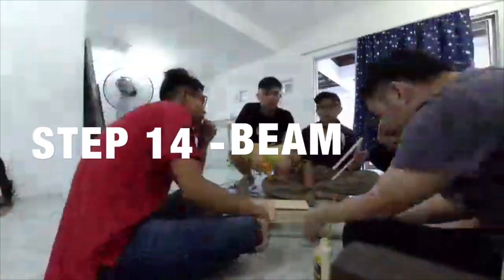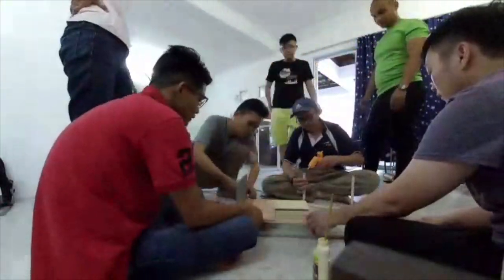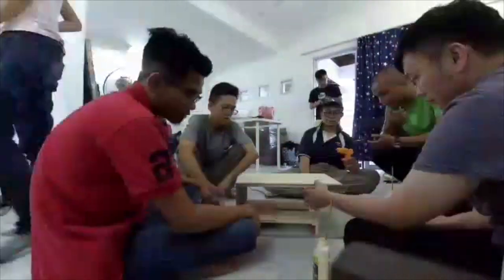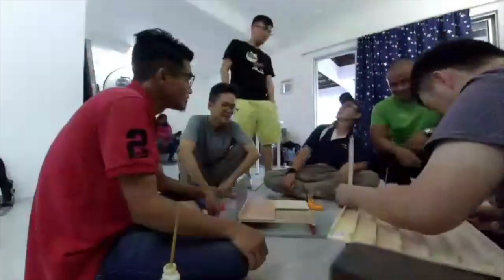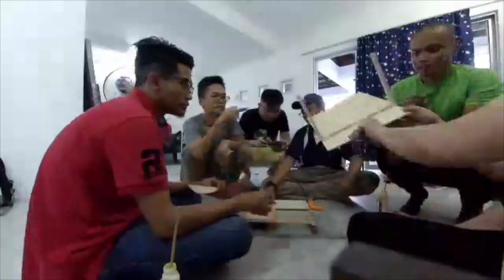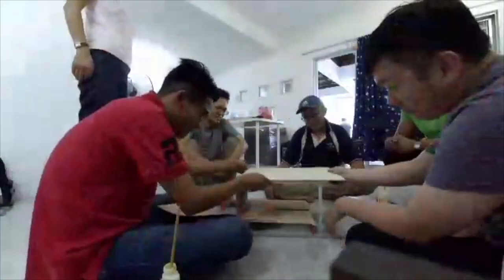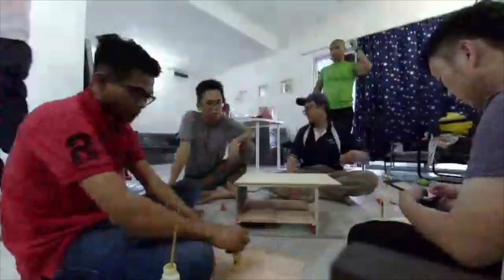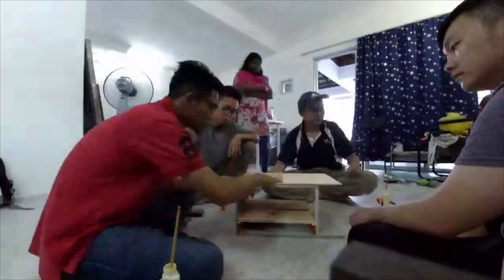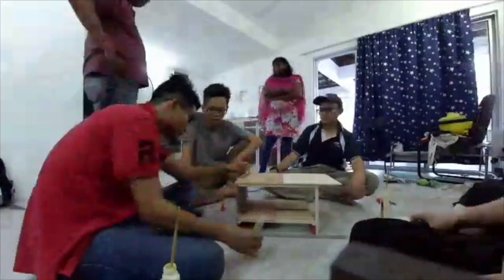Beam is also an additional element. Beams are horizontal structural elements that resist loads applied lateral to their axis. Typically, they transfer loads imposed along their length to their endpoints, where the loads are transferred to the wall, columns, foundation, and eventually to the ground. On the working model, we are using balsa wood strip. We glue the beam and it rests on the column.